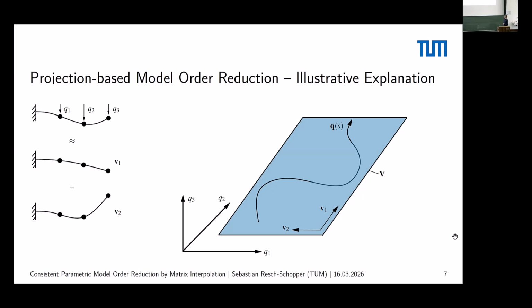So this could be the eigenmodes. And geometrically, this means that we take basis vectors in this space, and they span a subspace. You'll see these subspaces, as announced by Romain, multiple times today. So please keep this picture in mind. When we do the projection-based model reduction, what we're trying to do is to approximate our actual solution in this space. And if the space is quite appropriate and accurate for describing our full solution, then we get a good result with a much smaller computational complexity because we're just in this reduced space.